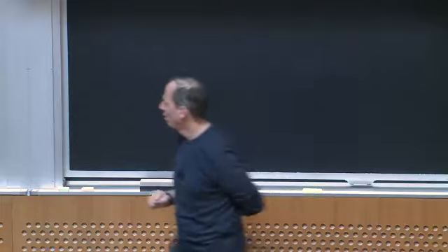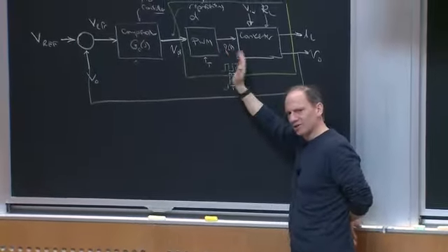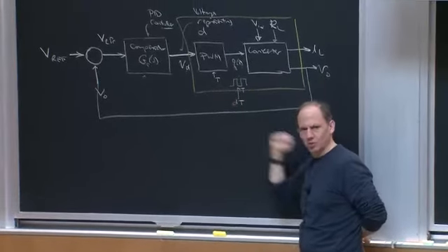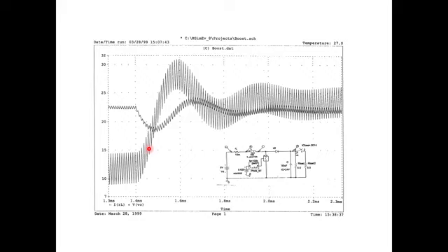My whole notion was that at least within a cycle, duty ratio is not something I'm swinging around wildly. So I'm interested in the behavior of this circuit for frequencies relatively low compared to the switching frequency. What I want to do is generate models that capture this average behavior, these low frequency oscillations, and ignore the switching ripple. Okay, everybody follow that?